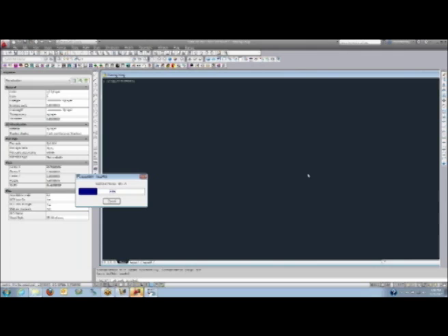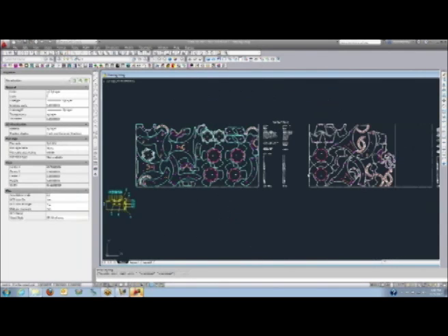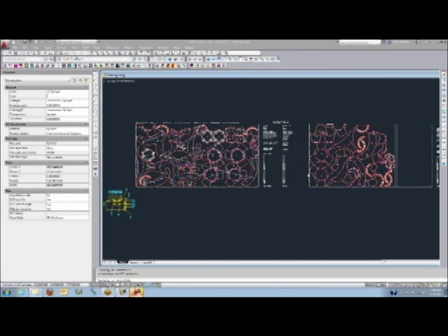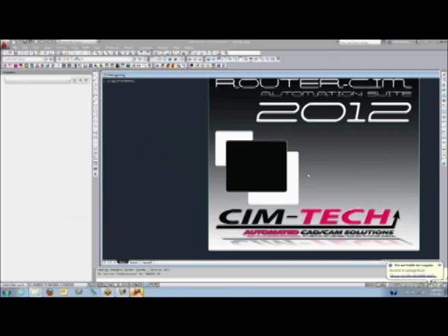Here's our nesting process beginning now. Parts are nested. And the layout is saved as an AutoCAD drawing. Again, we're using tool stay down nesting, which is one of the AutoCAD advanced nesting features that dramatically reduces your cycle time by keeping the tool down and connecting from part to part without lifting up.